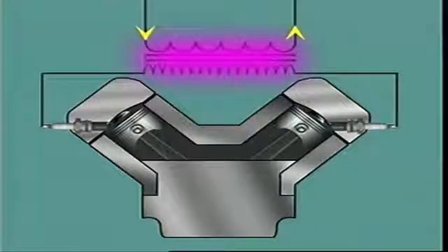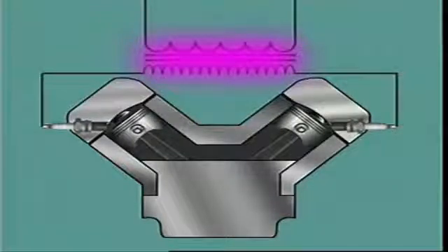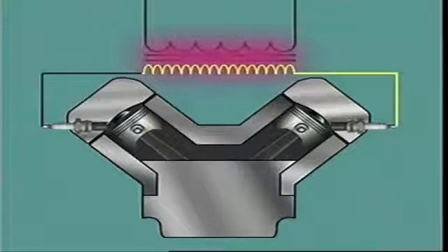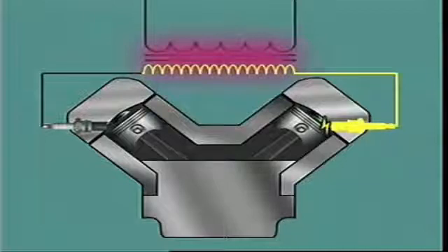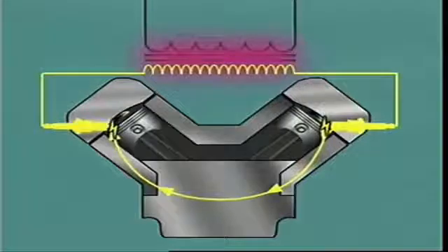The cylinder on compression stroke is said to be the event cylinder, and the cylinder on the exhaust stroke is the waste cylinder. When the high tension voltage is induced in the secondary winding, the secondary circuit is completed by current flowing through the high tension lead to the center electrode on one spark plug, bridging the gap and creating a spark in that cylinder, traveling through the cylinder block, bridging the spark plug gap in the companion cylinder, and flowing back through that high tension lead to its starting point.